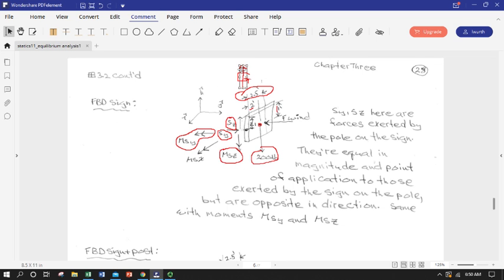Now the one that I always find a little bit less obvious is the fact that we are also getting some rotation due to that wind load around the I-hat axis, the wind and the weight. So the sign is actually going to have to apply another force, or excuse me, another moment, not a force, but another moment in this direction. And if you want to think about it, it's because we're looking at, again, twisting, so we have to do some envisioning.